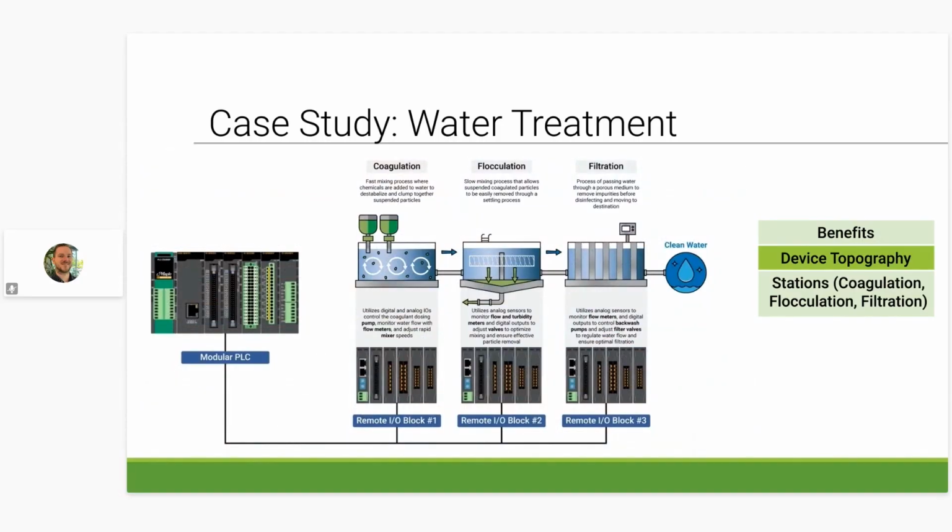Because analog sensors are a necessity within water treatment plants, in order to measure tank volume or pH level as an example, remote I/O becomes even more important. As we discussed previously, the longer the wires run from the PLC and local I/O to any analog sensors in use, the more negative the effect on their reading accuracy.